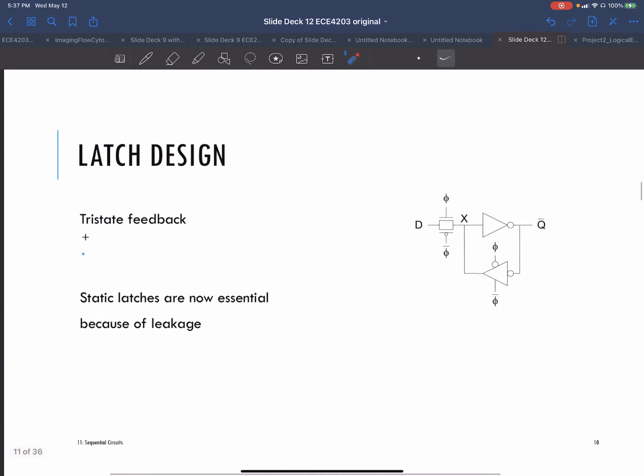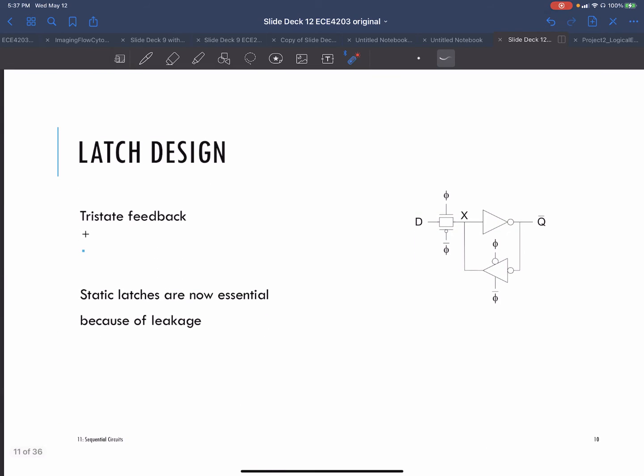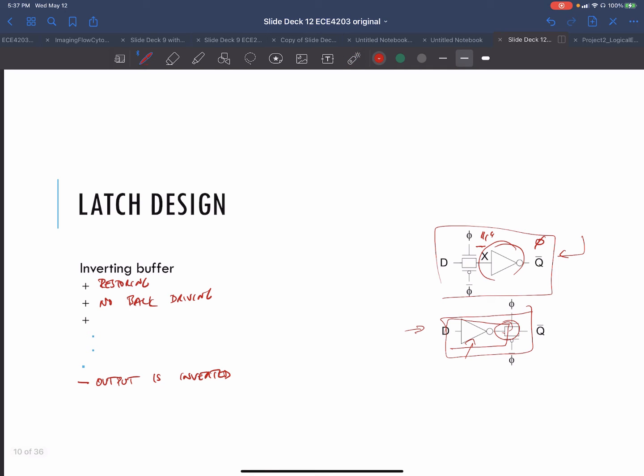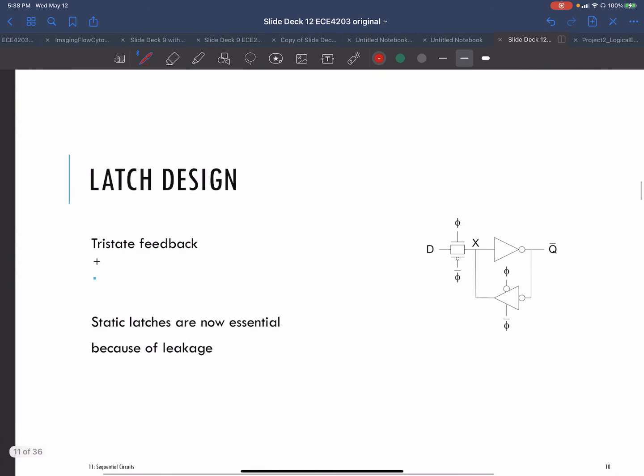Okay. The next step was, so all these things so far are still dynamic latches. You're storing this value in some capacitance out here. Then the next step was to create a static latch, and the idea was to create a so-called back-to-back inverter stage. So imagine if D was high for a second, if D was a 1, the output at Q bar would be 0.